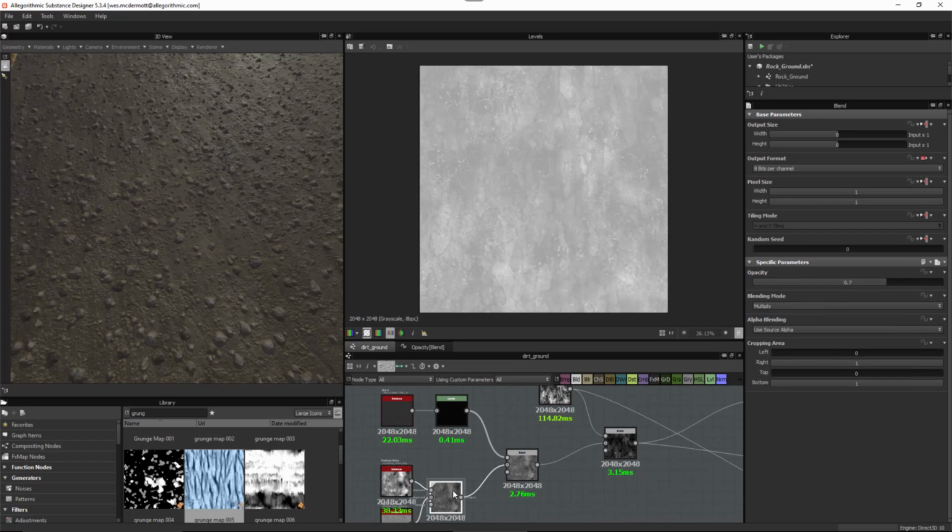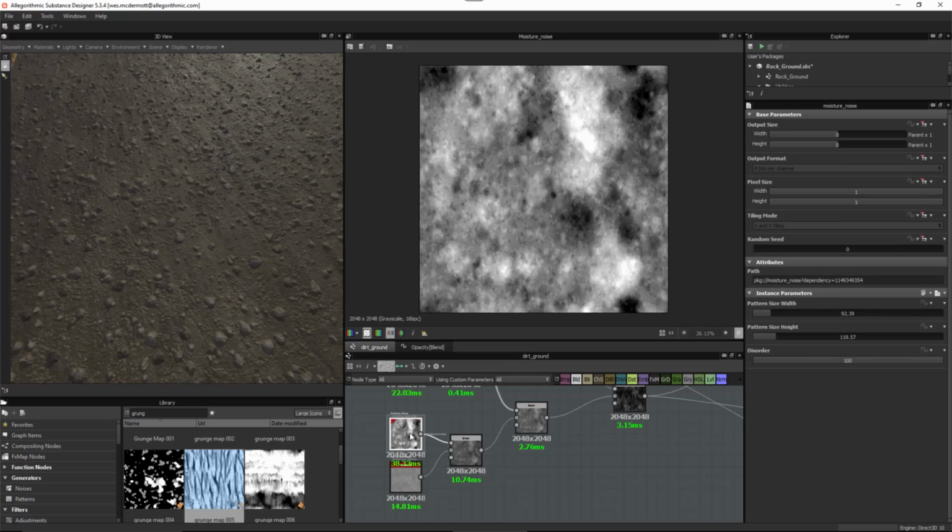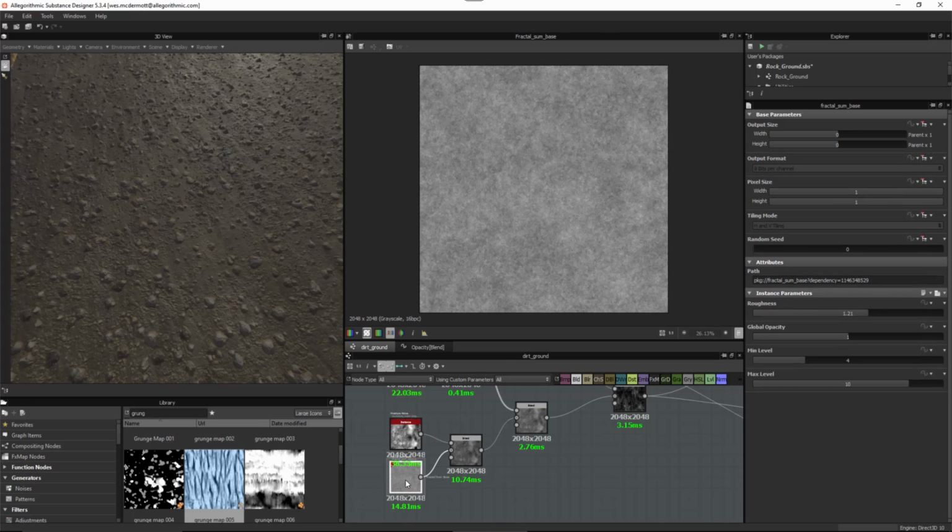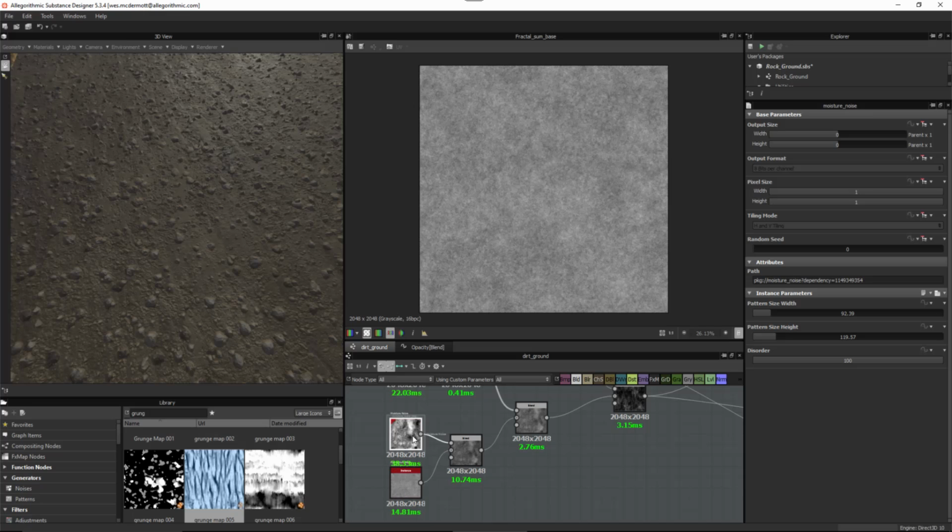Yeah, here you can see I have this blend node, and these noises, notice that they're operating at 16-bit internally, and we can't really change these with this output format. So if I select this one and set it to absolute 8-bit, internally it's still going to be working at 16-bit. So I had these 16-bit noises, but I don't really need 16-bit for what I'm doing here, feeding a grayscale value to my normal as well as my roughness.